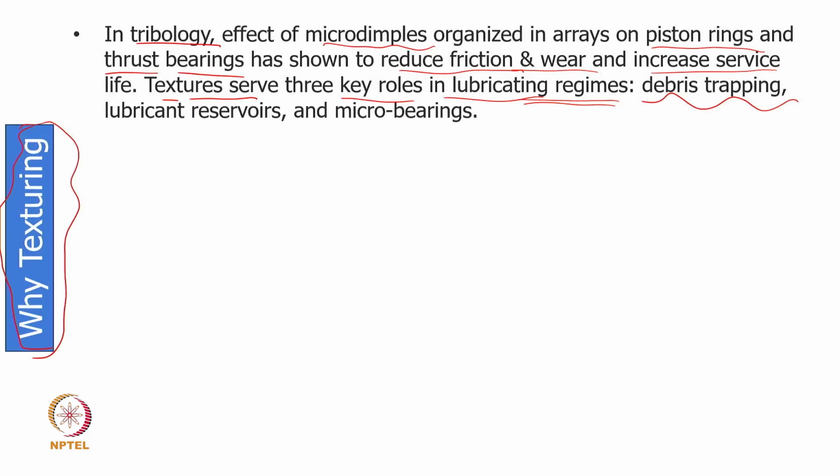So, this acts like a pocket, and whatever debris there is gets dumped there; I use the word dustbin. And then this can also act as a surface to keep a reserve of lubricant, so even if the pump fails in between, at least we know the lubricant is there. So, the product will survive for some more time.